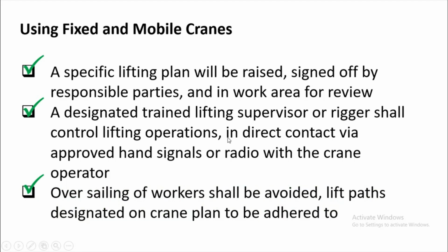Oversailing of workers shall be avoided. The lift path designated on the crane is to be adhered to. So this is the one I told you about already. When you are planning to have lifting operations, or lifting with a crane, you need to identify those workers below your lifting direction, so that you can eliminate the presence of workers in those locations.